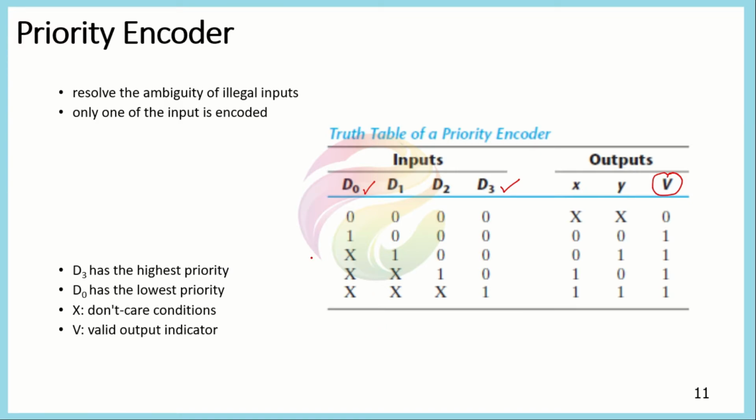Say if we are representing x 1 0 0, it is actually representing two different minterms. One is 0 1 0 0 and the other is 1 1 0 0. So it means that x could be both 0 and 1, and this one term is actually representing two different minterms. Similarly, in this case, there are two x values, so this will be representing four different minterms, and this one will be representing 8 different minterms here.